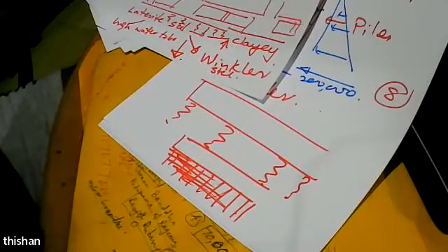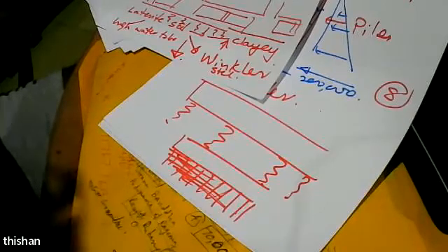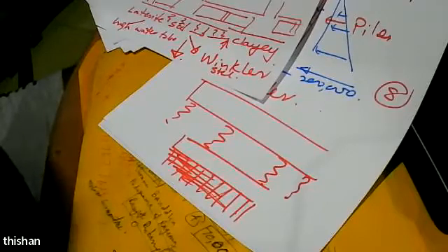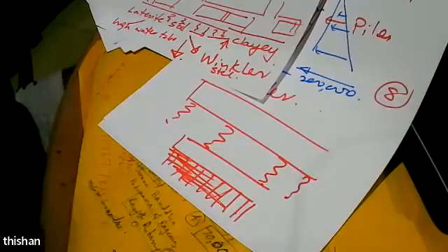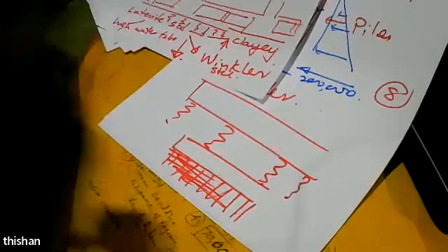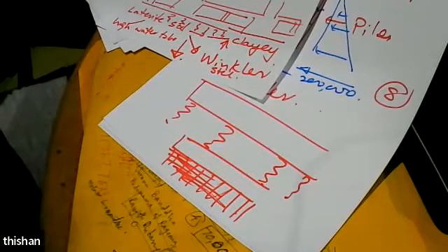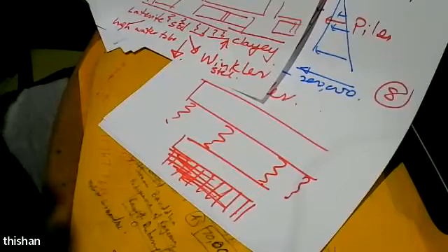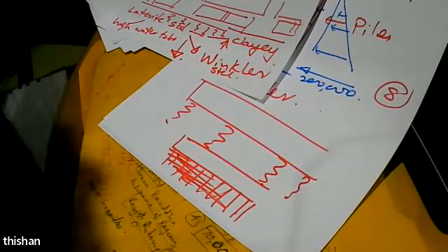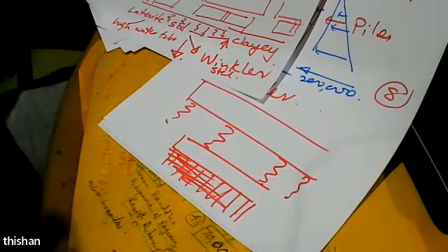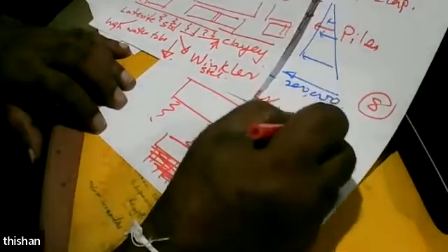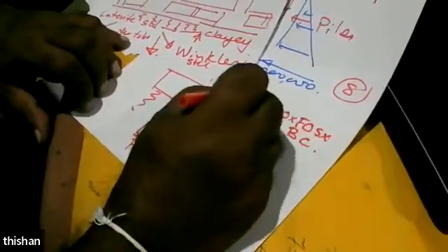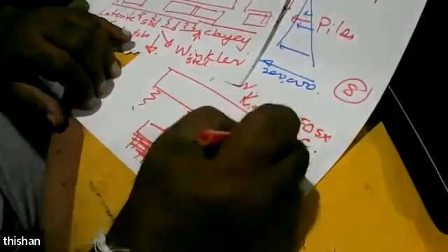Yes, so I have explained the fundamental aspects of modeling. I gave little pauses because I just wanted to make sure we have time to understand what I said. So you can see it goes to a very sophisticated level, that the same soil, the depth of the water table can decide whether it's going to behave more like a clay soil or more like a sandy soil. The sandy soil, very easy, springs. And you'll ask what is the spring constant for vertical, and we say it is 40 times factor of safety times bearing capacity. So that is the K of springs. And you'll get the answer in kilonewtons per meter cubed.